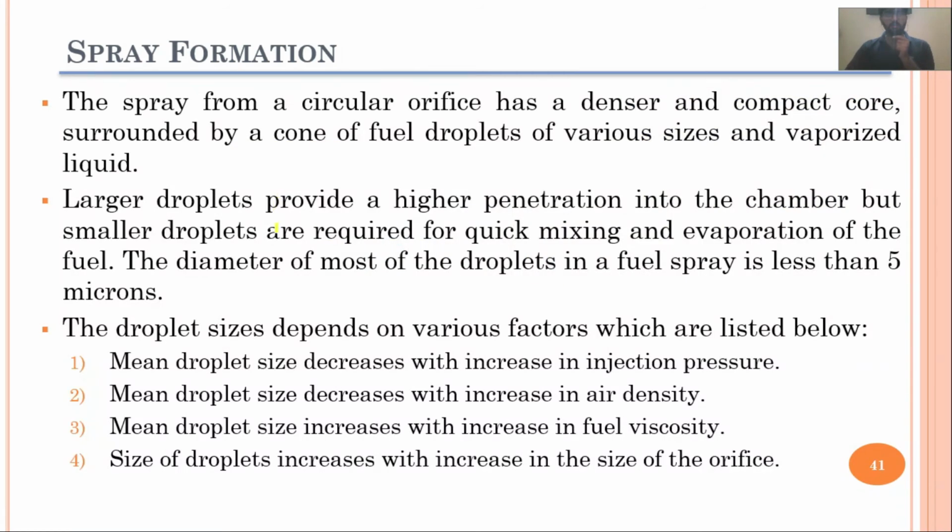And now moving forward, the spray formation from a circular orifice has a denser and compact core surrounded by a cone of fuel droplets of various sizes and vaporized liquid.